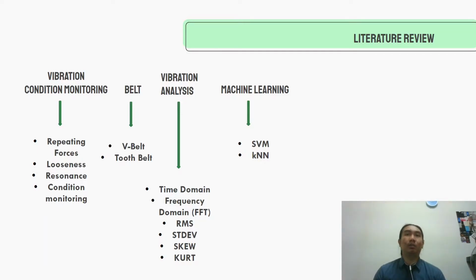The RMS, which is root mean square, value is commonly the most helpful because it is directly related to the energy content of the vibration profile, and thus the damaging ability of the vibration. The standard deviation is a measure of the variability of a signal about its mean value. For a vibration signal with a mean value of 0, the standard deviation is equal to the RMS value of the signal.